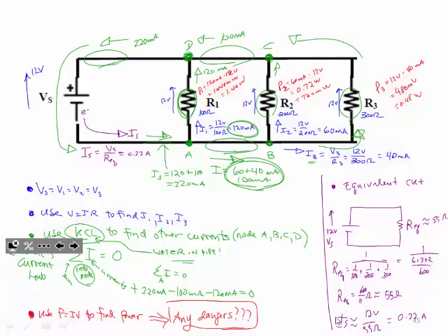All right. So your equivalent circuit here. My equivalent circuit is replacing these 3 resistors with a single resistor. So the battery wouldn't know the difference between one versus the other. And remember, for a series circuit, it's easy. It's add the resistors together. For a parallel circuit, you got to add the reciprocals and take the reciprocal.